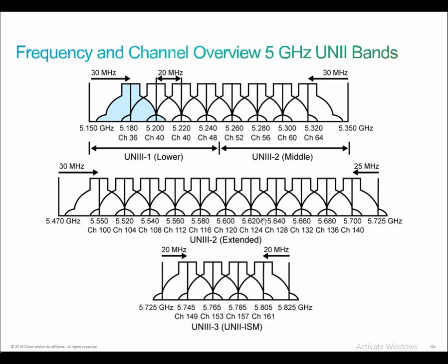You can see the 5.15 gigahertz to 5.25 gigahertz range, which is what they call the UNII-1 or lower band. The FCC limits the power of this lower frequency range to 17 dBm, and it's identified as for indoor use only. ETSI says that you can have an effective isotropic radiated power of about 23 dBm in this case.